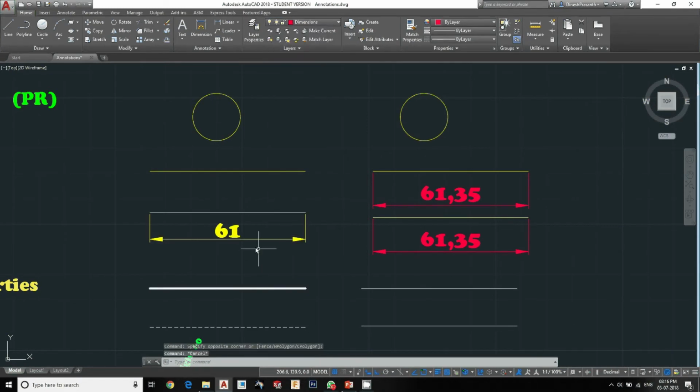Unfortunately, I made this dimension style with the help of the dimensional text layer, but I have to make the dimensional things unique. In most industrial drawings this is preferable, and it will help you finish the drawing in easy, short steps. So I'm going to use match properties.